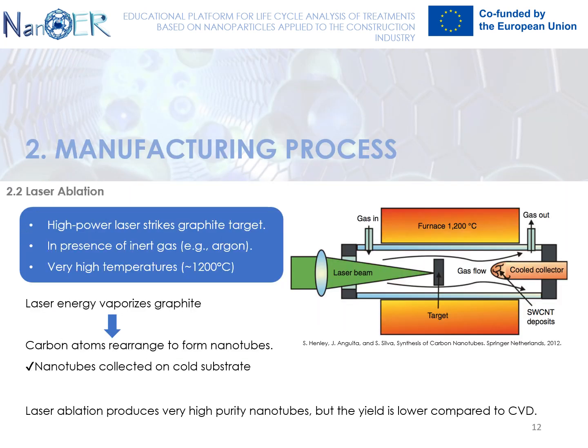Laser ablation as a method is a recent discovery for producing CNTs. It's also called pulsed laser vaporization. The technique functions like electric arc discharge. It vaporizes the carbon, which is then deposited on a substrate surface. Specifically, laser irradiation vaporizes a piece of graphite target, which must be pure, under high temperature under inert conditions.